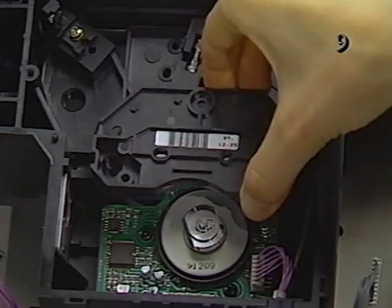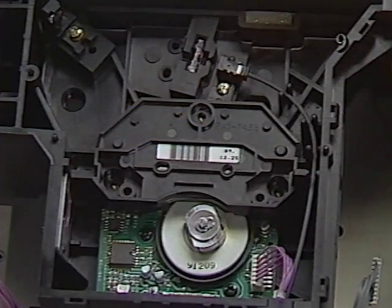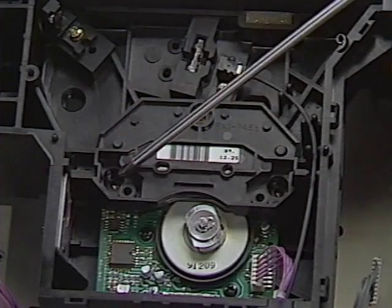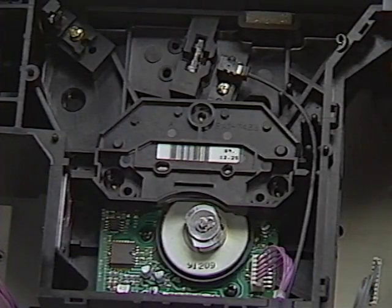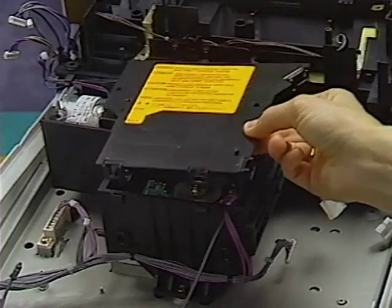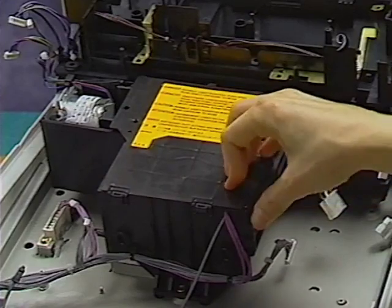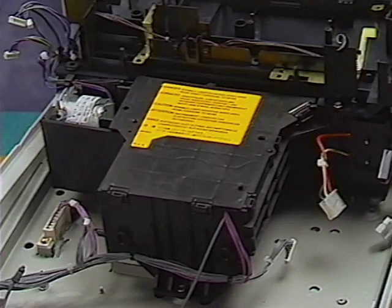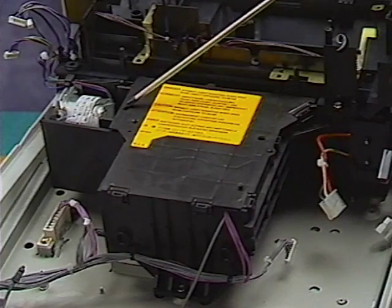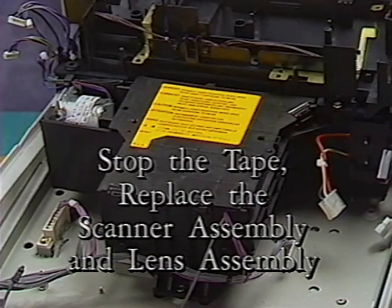Next, carefully lower the lens assembly into position inside the scanner assembly case. Replace the 3 black screws that hold the lens assembly in place. Now replace the scanner assembly cover and secure the 4 cover hooks. Finally, replace the large silver screw that holds the scanner assembly cover in place. Stop the tape and replace the scanner assembly and lens assembly.